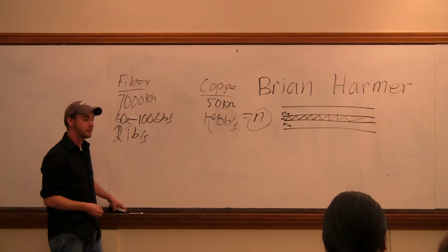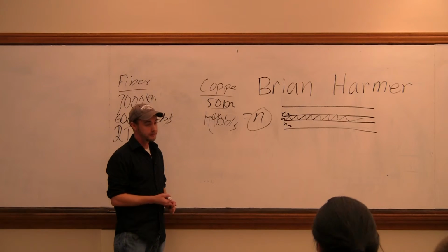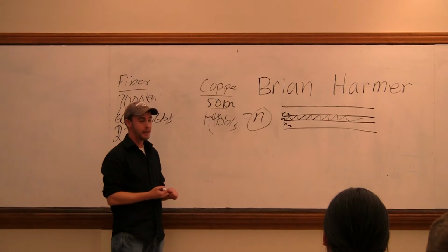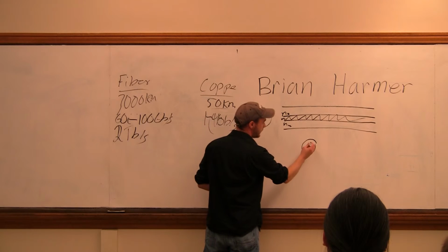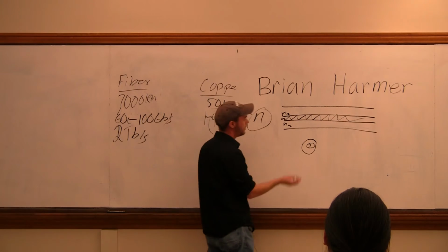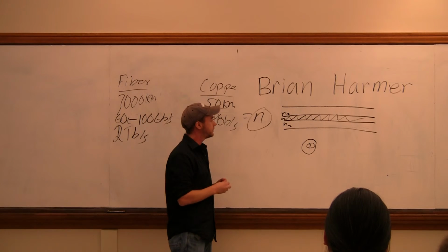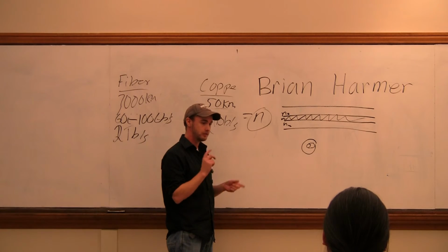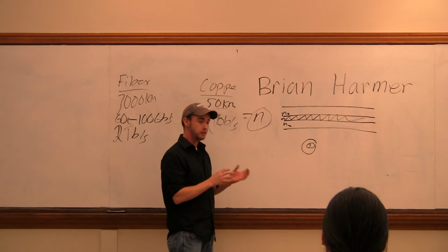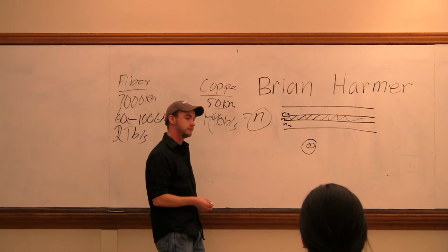So what is the cladding made of? You can do glass, or glass and plastic, or plastic and plastic. If you think of it in 3D, it's a very minor difference in the material structure, but it's just enough for the light to continue on like that. It depends on what type of system you want. If you want a small-range, short system with high losses, you can do plastic. If you want really good data rates, you want to have glass.